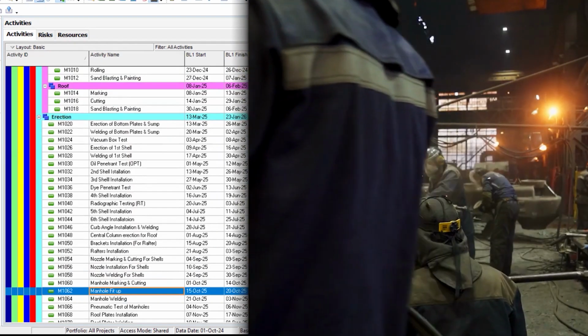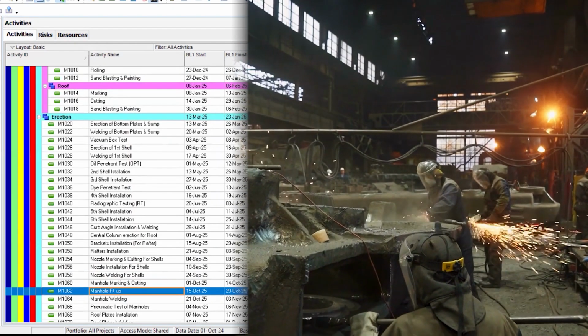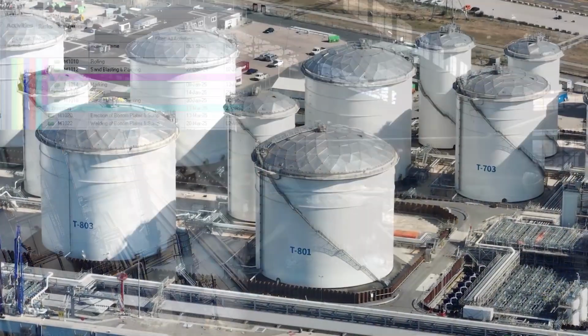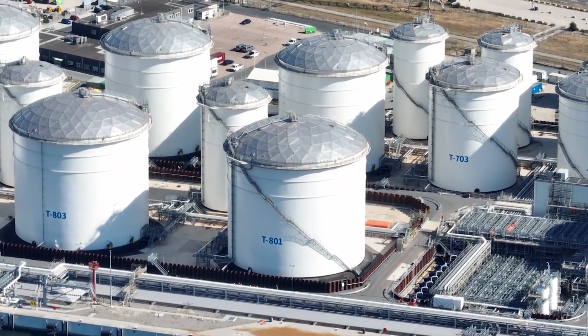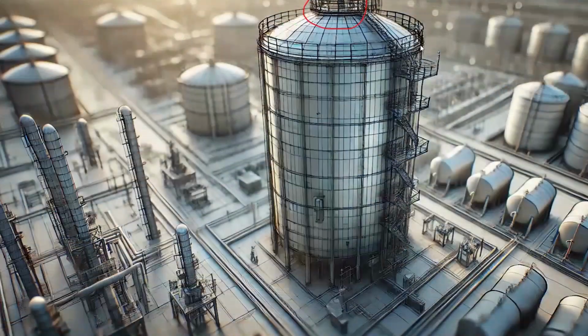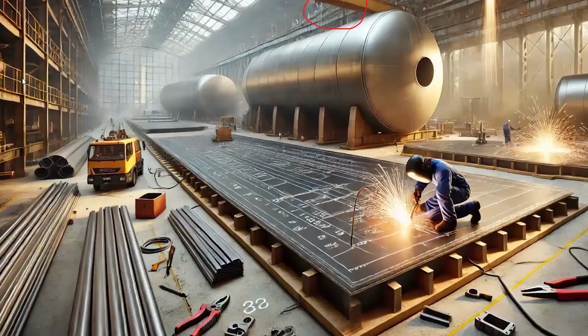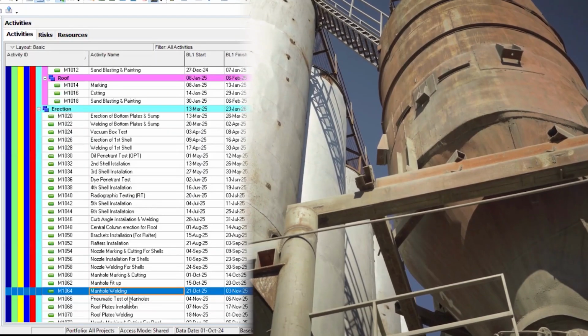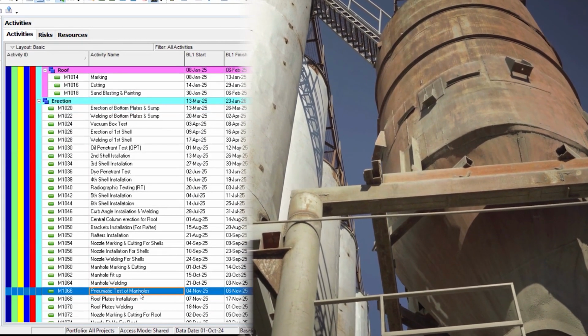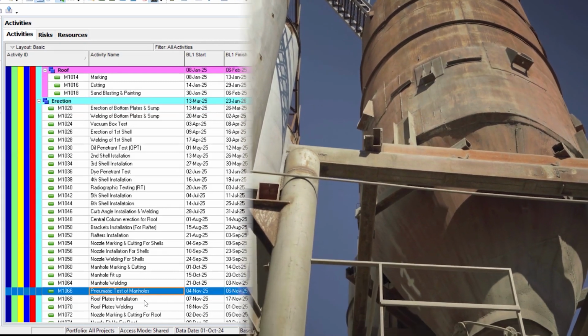So this is supposed to be like a manhole, right? Over here. But when we are taking the horizontal review, so see, this would be the manhole. Okay. And then I'll be sharing again manhole welding. Obviously, you are going to weld this one. Pneumatic test of manhole. You are going to make pneumatic testing with the usage of air.